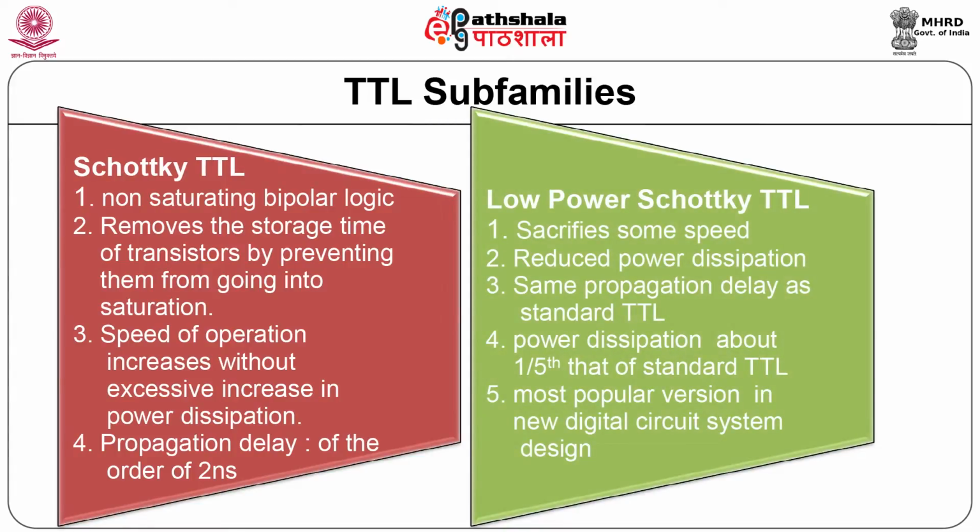Low power Schottky TTL sacrifices some speed and has reduced power dissipation. It has the same propagation delay as the standard TTL, but the power dissipation is about 1/5 of that of the standard TTL. Most popular version in new digital circuit system design.